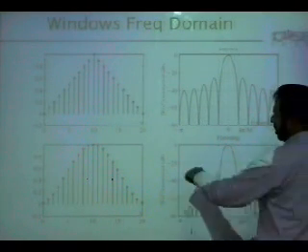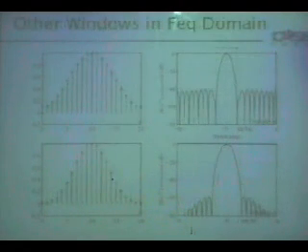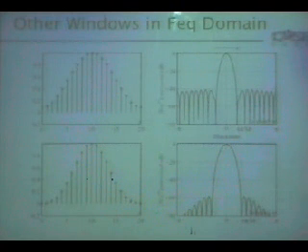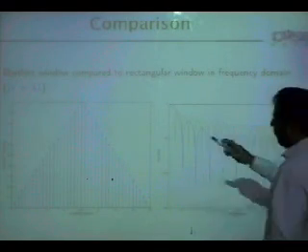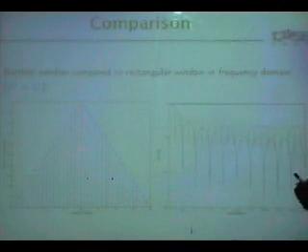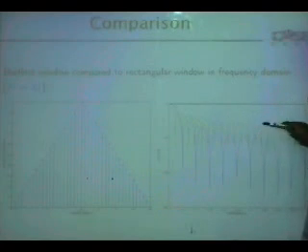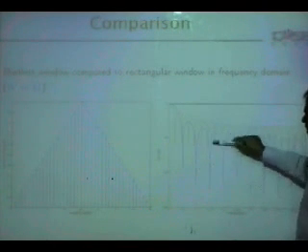The same length of window has this frequency response. Similarly, this is the Hamming and the Blackman window. A nice slide is where you see all of them together, so we'll shortly see that. This is a good comparison of a triangular window with a rectangular window, and you can see the trade-off. The same length, length is 41. As you can see, the triangular window is shown here, and what you see in blue color is the triangular window.